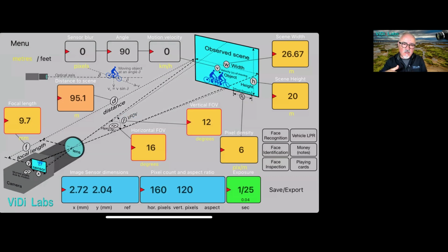So that's roughly an idea of how you can use the thermal calculation distances, knowing this thermal DRI, detection, recognition and identification, and be able to create or design a system where with different focal length lenses for the thermal imaging you achieve different distances.